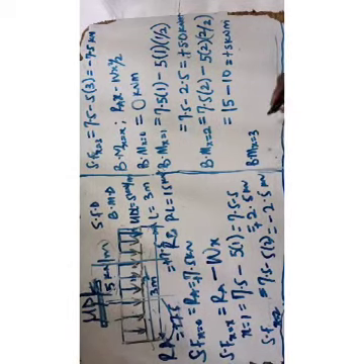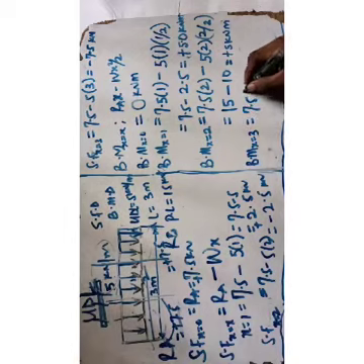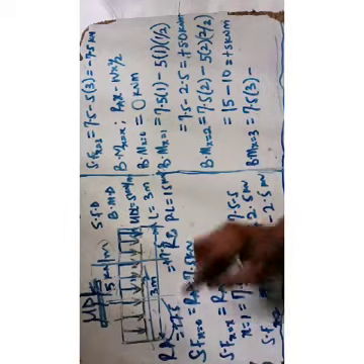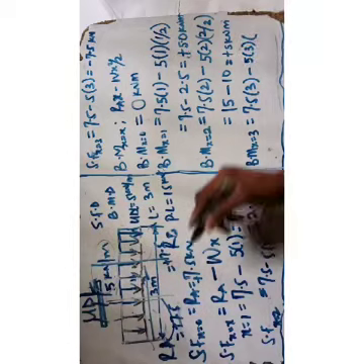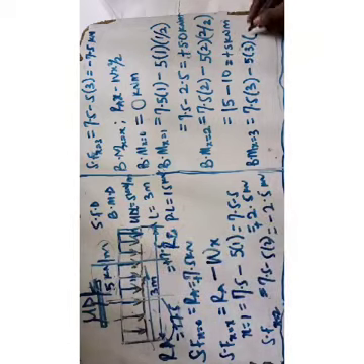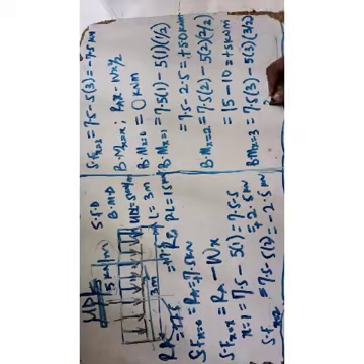So let's confirm that at x, that will be 7.5 times 3, right, minus 5 times the total length, that is for the 3 we are considering, 5 times 3 multiplied by 3 over 2, that is 1.5, and you have this as 22.5 minus this is 15, and you have this as 22.5 minus 22.5 because this is 1.5, yeah, and you can have your answer as 0 kilonewton meter, okay.